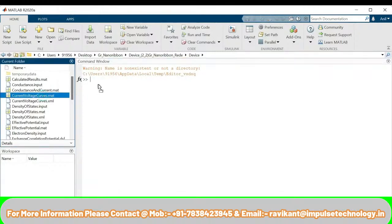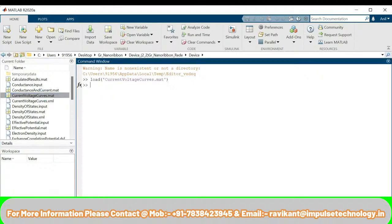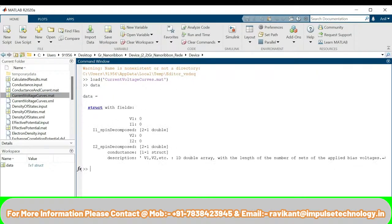Current voltage value. Then you can load this current voltage curve .mat file, that is a MATLAB file. I have loaded the file. Then type data. It will show that voltage at contact 1 equals 1 and current equals 1. Voltage at contact number 2 equals 0 and current equals 0. Since I have not applied any biasing, that's why the current on electrode 1 and electrode 2 both are 0. If I apply the biasing, then the current will change.